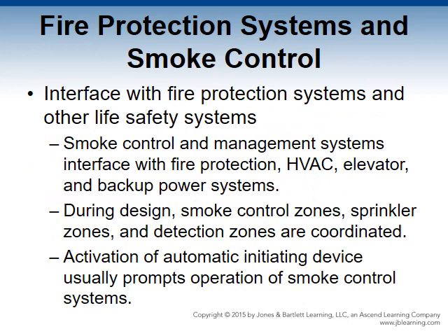Interface with fire protection systems and other life-saving systems. Smoke control and management systems interact with your fire protection systems, HVAC systems, elevator systems, and backup power systems to initiate the appropriate control sequence and response when a fire emergency arises. During the design phase, smoke control zones, fire sprinkler zones, and fire alarm and detection zones are coordinated to establish the operational relationship between them.